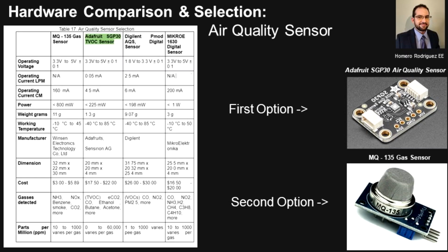Air quality is an important parameter to consider in our research. Choosing the best option is key for producing reliable data that can be stored and used. The Adafruit SGP30 sensor was selected not only because the price is competitive with respect to other options for its reliability, but also the wide range of projects that are currently using it, which translates into robust community support. It has been tested and debugged many times. It also counts with low power mode features and is native to Arduino, which makes it more attractive for our project. Even though we did not consider the MQ135 as our second option during Senior Design 1, after testing different hardware empirically, we found that it could be an excellent option as well. It worked out properly and is still good enough to provide reliable data.